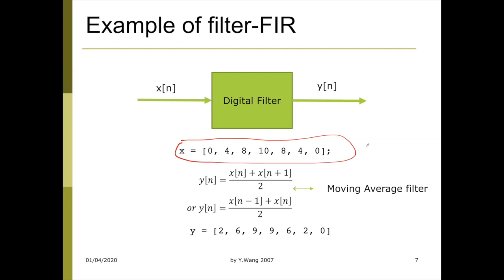So a simple moving average filter will improve the sensing process massively. It's very useful, although it's very simple. Rather than directly taking those signals, they apply a small average filter. So this is a moving average filter. They make decisions based on a filtered signal, which is yn.